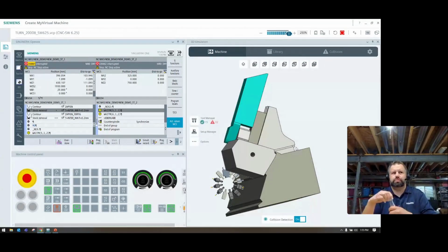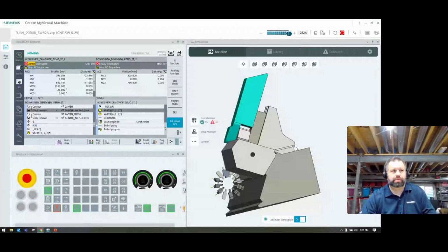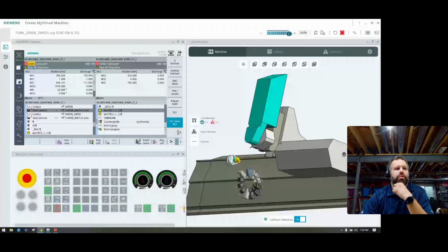But when you get to a large feature, you don't need a lot of linear speed out of your axes because you're talking about surface footage at that point, right? I'm out at a 3 foot diameter feature. I don't need that tool running around that really fast. Maybe on a big lathe, I might only be running that thing at 50 RPM or something to get some serious surface footage. So it's like anything else. It's another bullet in your belt, so to speak.